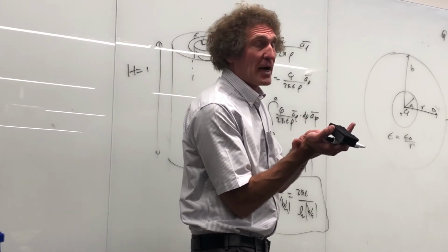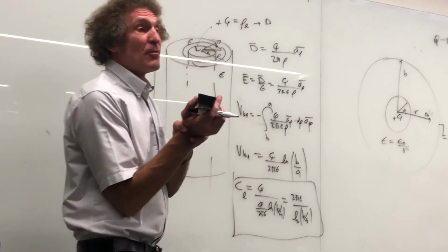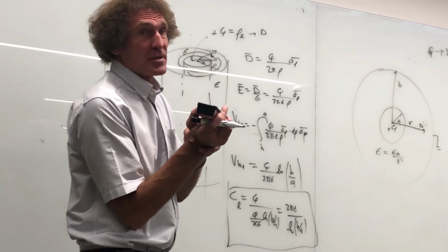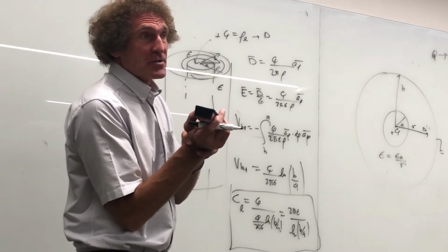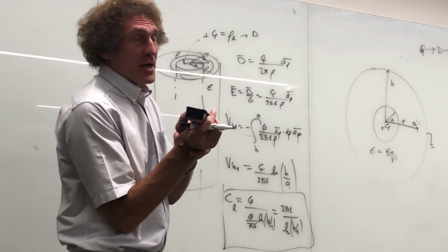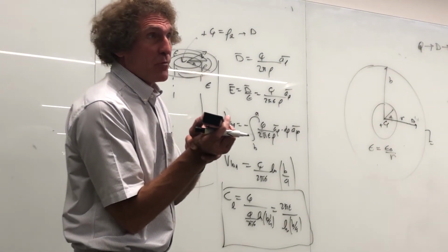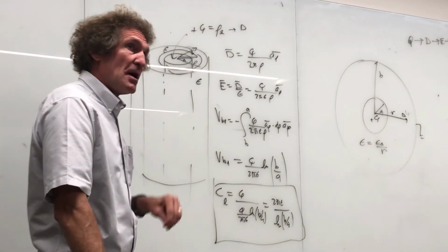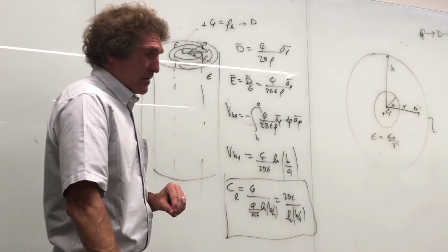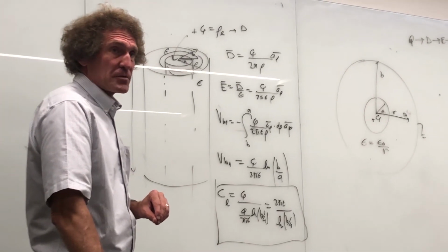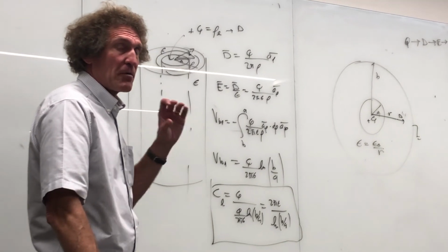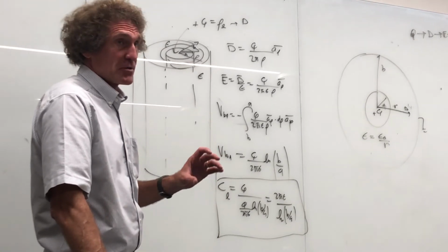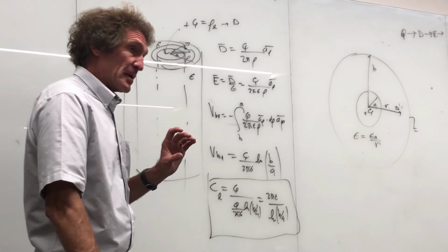If you want a supercapacitor, it's usually rated around 10 volts. Whenever they hear the term supercapacitor, put more than 10 volts on it, it'll punch through the dielectric, and it's usually not self-healing, so your capacitor is doomed. But if you want something that can withstand a lot of voltage, like if you're going to use a capacitor for some sort of filtering at say 200 volts, 300 volts, then you want something with a fair amount of dielectric strength, something that won't break down. And that means a much larger capacitor for a given amount of charge handling ability.